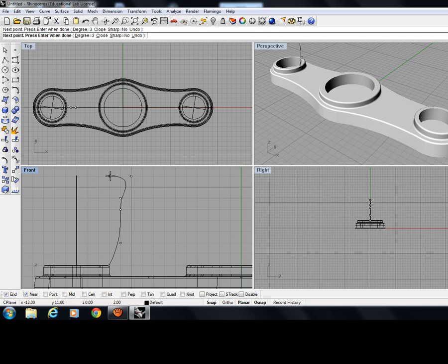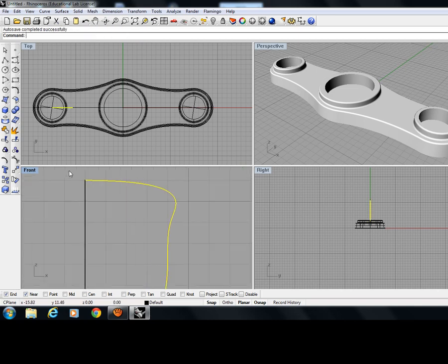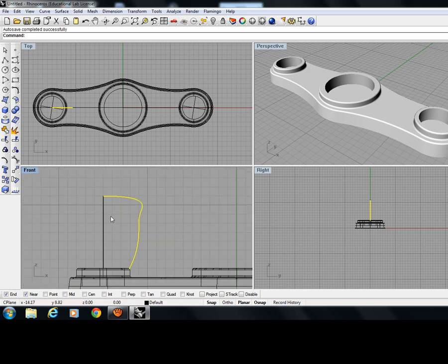As you see, I'm going to make this revolve just on the top of the axis because I want it closed completely. Press enter and I have my curve, and I want to take it all the way to this point because I want it closed. I want a closed revolve. Now after I have this, I need to record history. Recording the history of my revolve, that way I can change it after I have the surface.